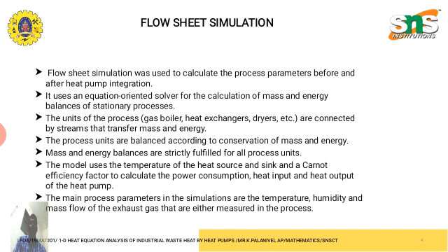And next one, flow sheet simulation. Flow sheet simulation was used to calculate the process parameters before and after heat pump integration. The simulation tool IPSE Pro was applied, which is well studied for industrial processes. It uses an equation oriented solver for the calculation of mass and energy balance of stationary processes.